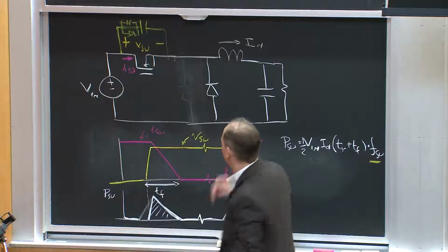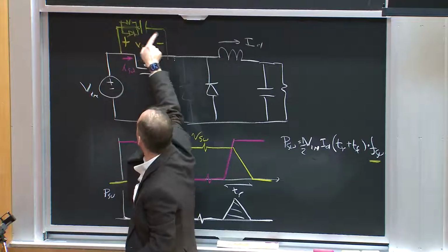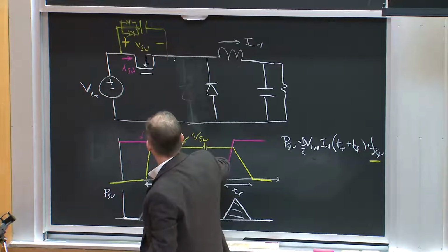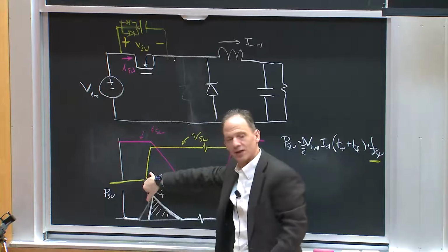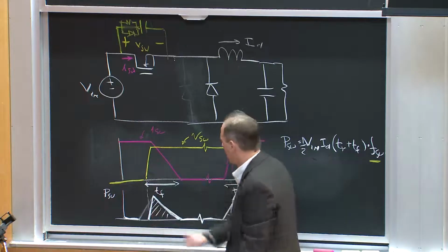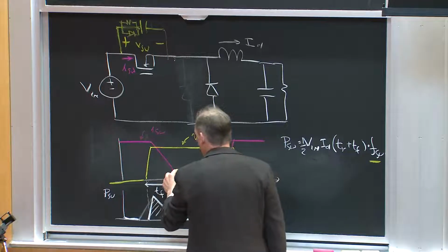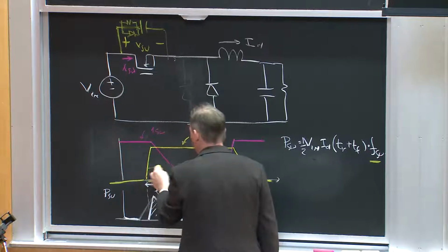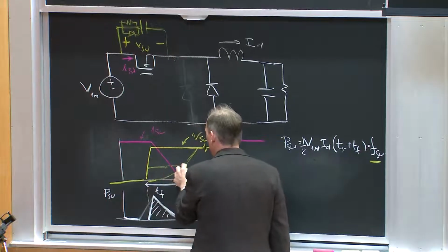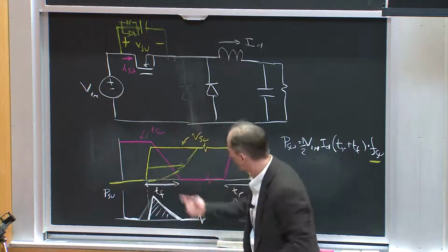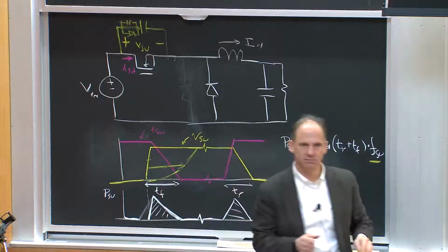If I did that, when I turn the transistor off, I have another path for current to go through, and I can charge up this capacitance, so voltage doesn't need to rise so quickly, right? So if I put this kind of circuit in, I can delay the voltage rise on the device. It might do something like this, so I push this out here, and I reduce the VI overlap, and instead of a fast rise, I get a slow rise, okay?